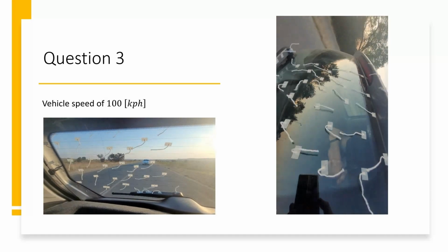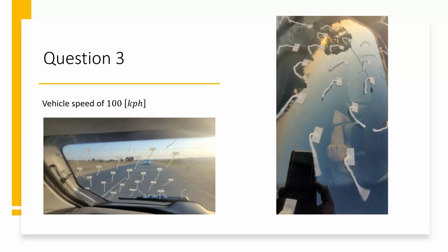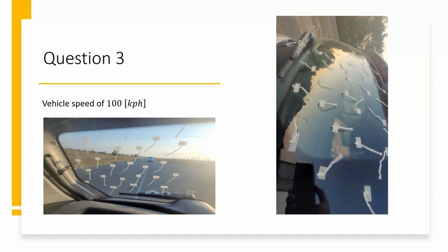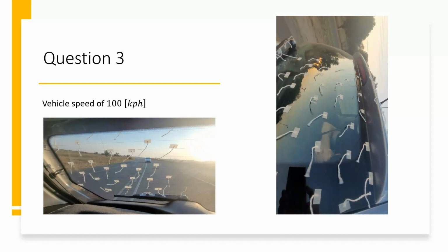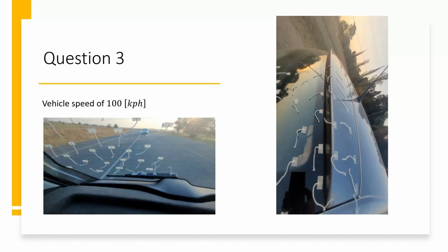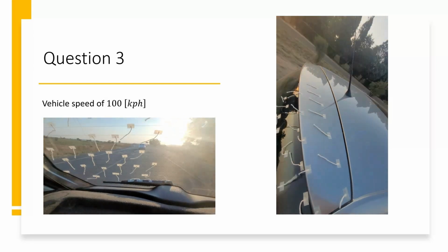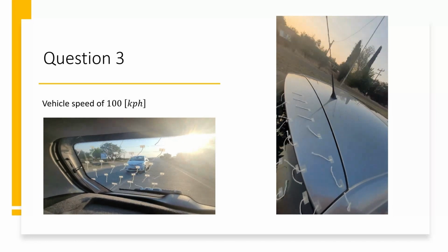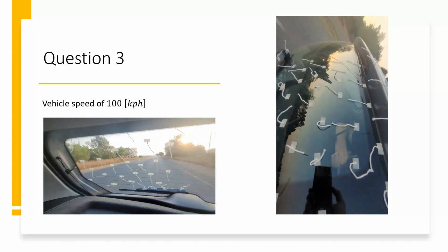The tufts placed on the rear window moved in an extremely radical and random manner with no constant pattern, indicative of highly turbulent flow. This creates a large low pressure area over the rear window and back of the vehicle, which sucks in dust and debris thrown up by the wake the vehicle leaves behind as it travels forward. This dust and debris sticks to the rear of the vehicle, including the rear window, and builds up over time, making it hard to see through the rear window.